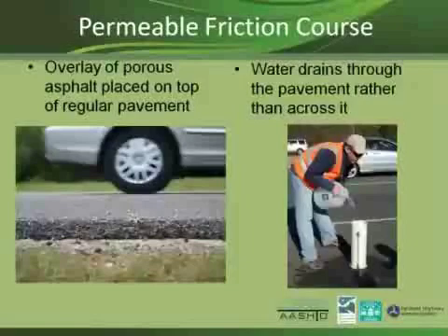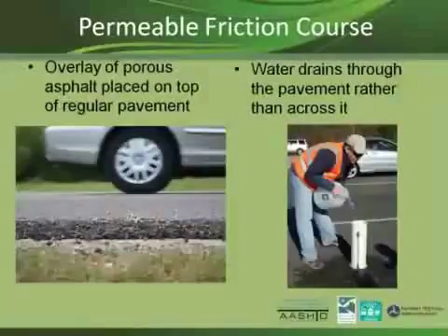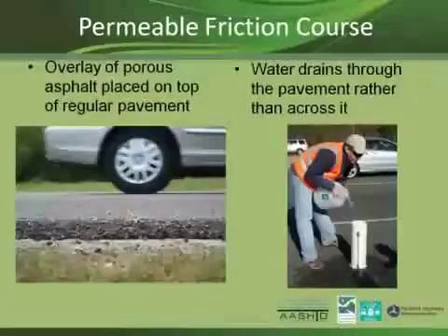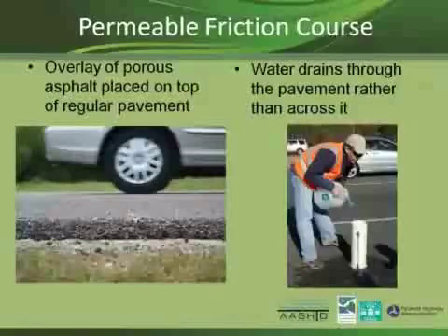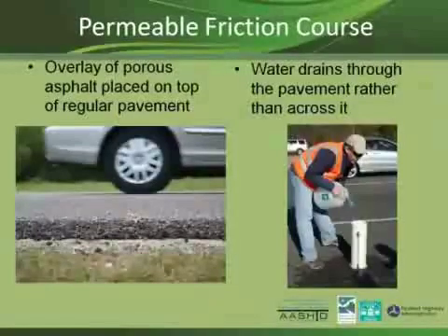So we're just talking about a thin lift porous overlay, and the reason DOTs are comfortable with it is that you have the impermeable layer underneath it, so it's not a fully porous section, and there's no concern about base materials getting wet and strength of the roadway and all of those kinds of concerns. Next, Eric.